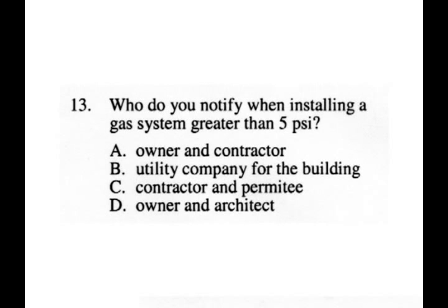Number 13, who do you notify when installing a gas system greater than 5 psi? The answer on this problem is letter B, utility company for the building. The gas company will tell you whether it's possible to provide a higher pressure system or not.